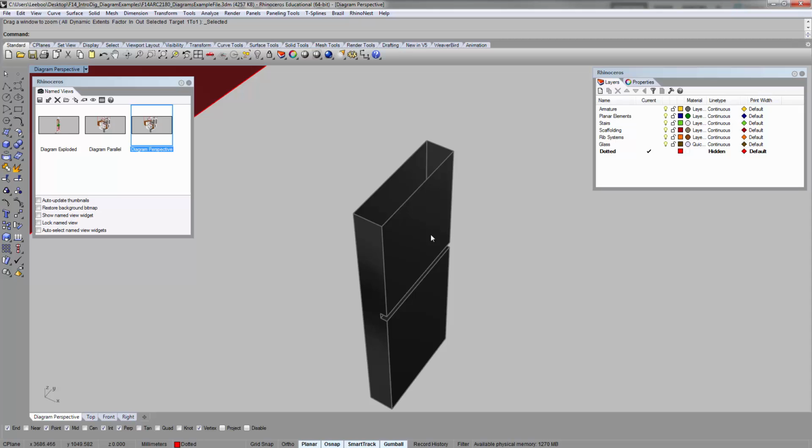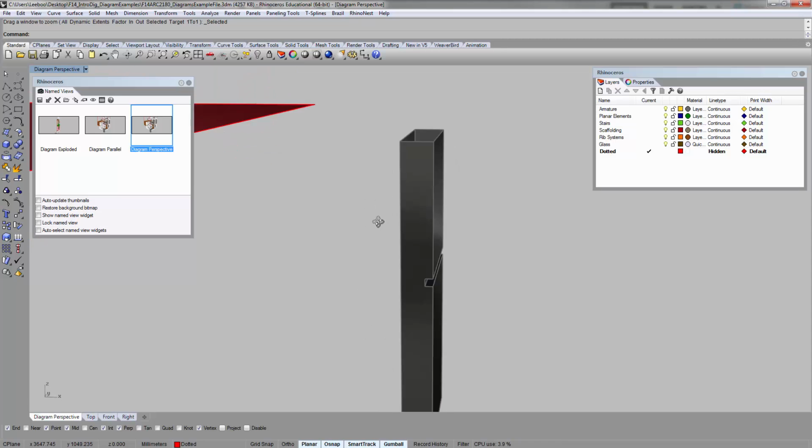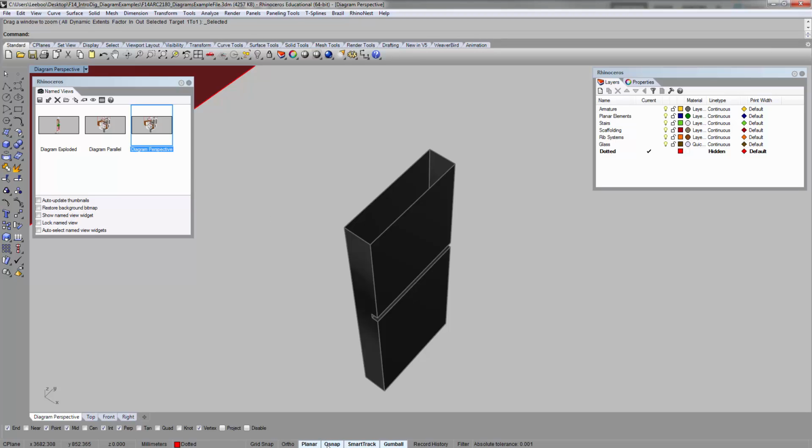But if you're trying to fix this, usually what I would do, and you have to make sure it's flat, right? Make sure your snaps are on, O snaps here is on, end snaps are on, right? And actually use a polyline, right? My shortcut is always L for polyline. I just use L all the time. And what you do is you basically snap to the 4 corners.